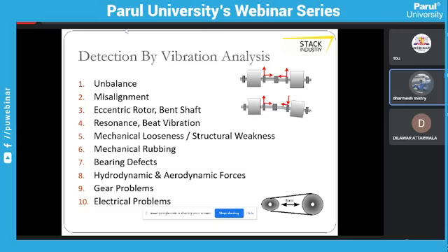A person who has to install a motor on a land, or is aligning anything, will understand at that time that yes, this thing I have to correct. Then the second image shows that there is some misalignment. In misalignment the shaft gets bent, due to which a condition called an eccentric rotor is created, and it will create vibration. So this machine will work for some time, and continuously it will go under breakdown. To avoid this maintenance cost, the vibration meters are also used during installation.